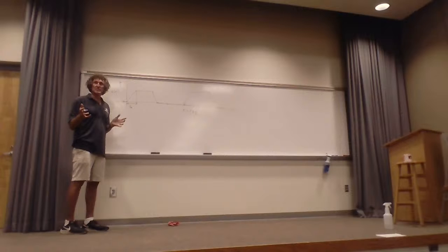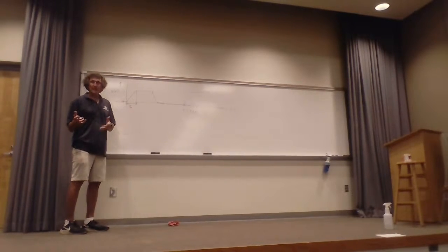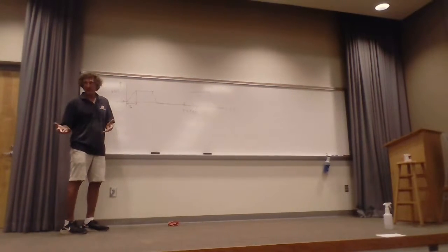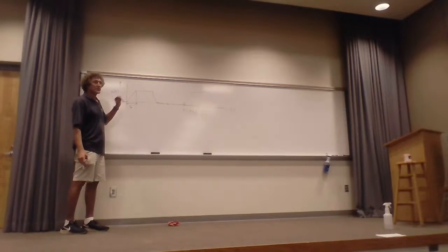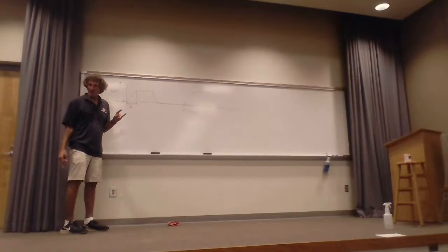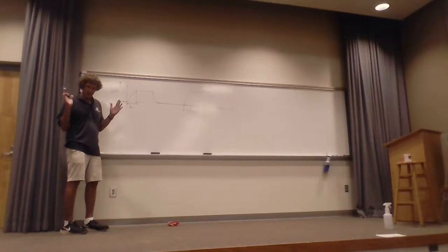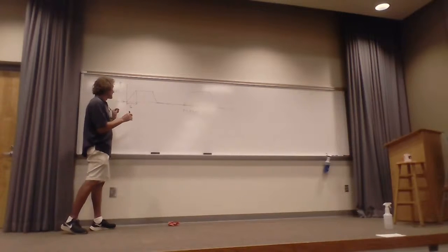There are differing opinions, but generally speaking, when we do analysis, radar work, electromagnetic compatibility, electromagnetic interference, or any type of meaningful analysis for design, they just approximate this whole thing as a straight line. They call that T-rise, and they always make sure it is the worst case value, typically the longest value, because you usually want a very fast rise time. You want that thing to get right up to value with no delays, because that way you can have smaller and smaller pulses and shorter duration time.